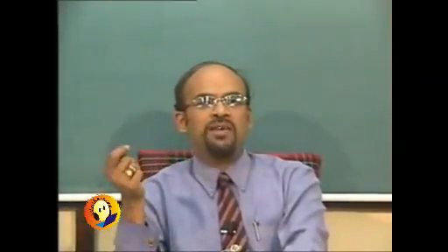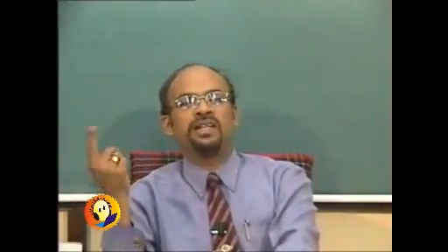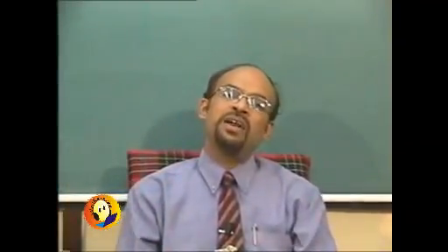Then from x and y we can find out velocity in x direction, velocity in y direction, and subsequently acceleration in x direction, acceleration in y direction, and we can very well determine the components of the force in x direction and y direction, and we can proceed with the application of D'Alembert's principle. So these are a few problems where the D'Alembert's principle can be used very easily.